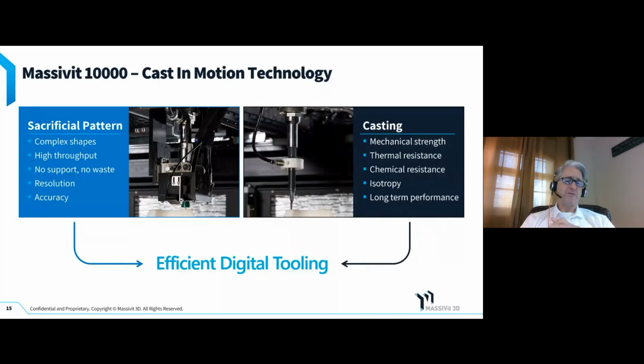Now, we do this for two reasons, the reason we're staging it. The primary reason is when a thermoset material cures or cross-links, it creates heat. It exotherms. And if you have a large mass, that exotherm really runs away from you and gets quite hot. So by printing 7 to 10 layers and then pouring, and then printing another 7 to 10 layers and then filling the gap with the epoxy,